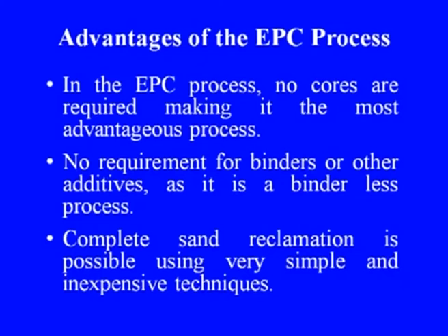Now, let us see the advantages of the evaporative pattern casting process. In the evaporative pattern casting process, no cores are required, making it the most advantageous process. There is no requirement for binders or other additives, as it is a binderless process. Complete sand reclamation is possible using very simple and inexpensive techniques. In this process, sand shakeout is easy, as the sand is unbonded.